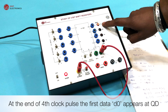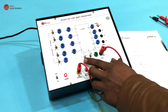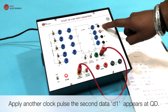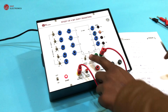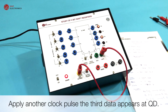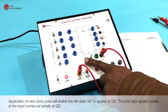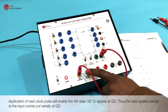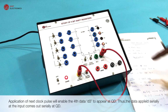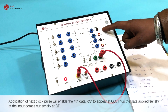At the end of 4th clock pulse, the first data, D0, appears at QD. Apply another clock pulse, the second data, D1, appears at QD. Apply another clock pulse, the third data, appears at QD. Application of next clock pulse will enable the fourth data, D3, to appear at QD. Thus, the data applied serially at the input comes out serially at QD.